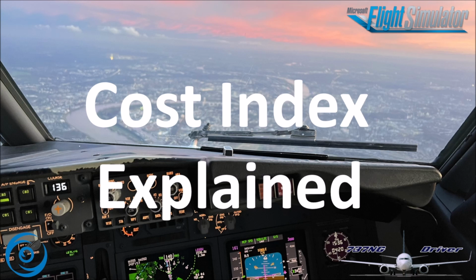And then on the lower left, it's going to give you the information what's the earliest time you can get there and what is the latest time you can get there. The earliest time would correspond to a cost index of 0, while the latest time would correspond to a cost index of 500.